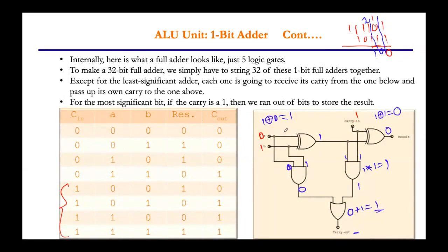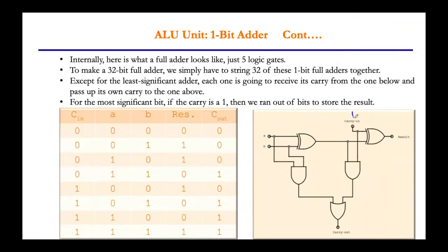Right? So now comes to the next one. Here now we have 3 ones, right? 1, 1, 1. So 1, 1, 1 means it is the case of the third operation. Carry in is 1. Your first operand is 1, second operand is 1 in this example. 1, 1, 1. It becomes 3. So let us see when carry is 1 and both the inputs are also 1. In our example case, 1, 1, 1, 0, 1 and 1, 0, 1, 1, 1. So here we got 0 carry 1.